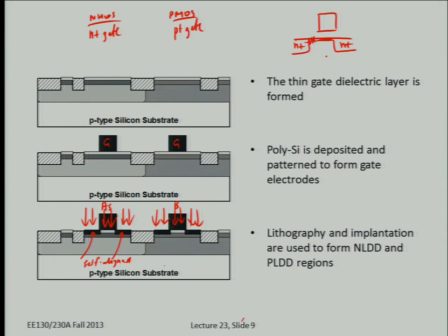So basically, if you don't have a self-aligned source drain region to the gate, then it can result in poor transistor performance. Or another way you can deal with that is just draw the gate larger, okay, to guarantee that even if you have misalignment between the gate and the source drain regions, you'll always be able to form an inversion layer all the way from the source to the drain. But if you have this particular case, then you have extra capacitance, and that can slow down your circuit, right? So you want to minimize the gate capacitance needed to form your transistor. So the best way is to perfectly have your source and drain region start kind of where your gate electrode stops. Okay, so that's very important.